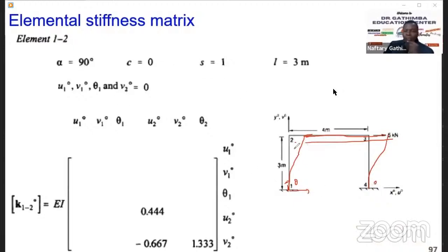So for this element, and again, if there's no elongation, the axial stiffness, maybe, of course, let me clarify this here. This could or could not, based on the flexural stiffness. But one thing that we know is that this member will not elongate. So it's kind of moving as a rigid body, but it can deform. Okay. The flexural rigidity may be not very high, but the axial rigidity, we are saying this length remains